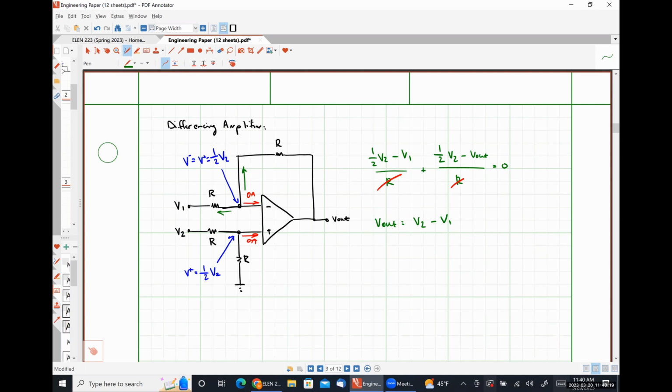DC is boring, right? But if we wanted to figure out what the difference between two signals was, so let's say that we had a message signal superimposed on top of a carrier signal in some sort of AM modulation scheme. This is how radio signals work. Well, if we subtract from that combination of signals the carrier signal, we are left with just the message signal. We demodulated it to get the information that was actually transmitted on top of that carrier, right?